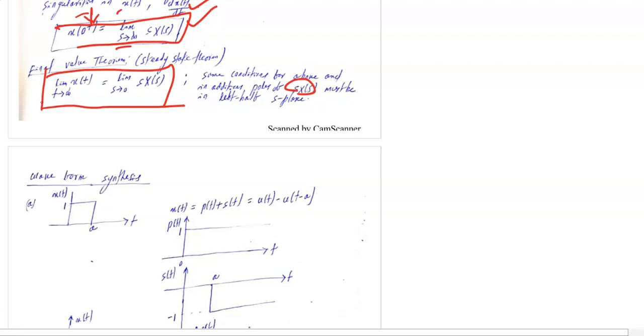So all the poles in the circuit elements, when you transform into the Laplace domain, you will not find any pole in the right half s plane. So we need not worry about poles in the right half s plane as far as circuit theory is concerned.